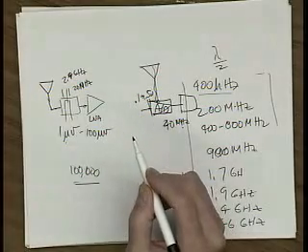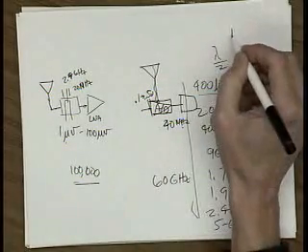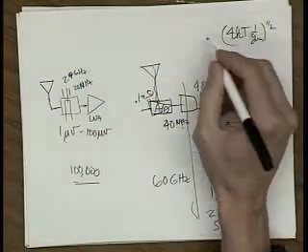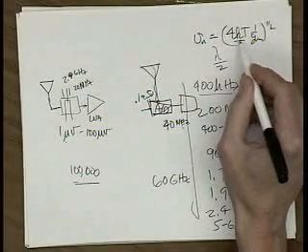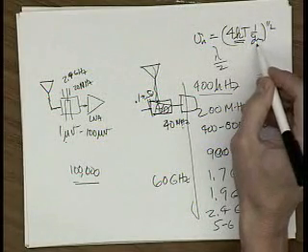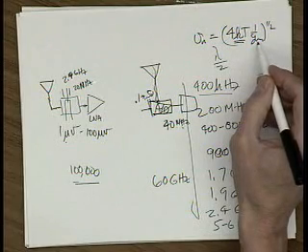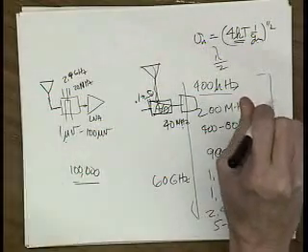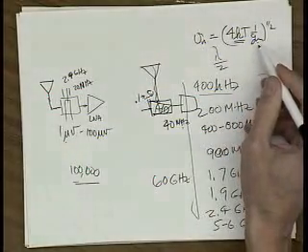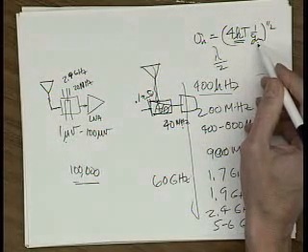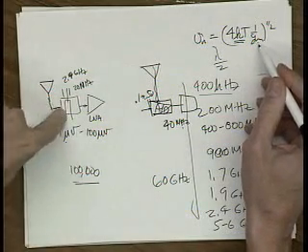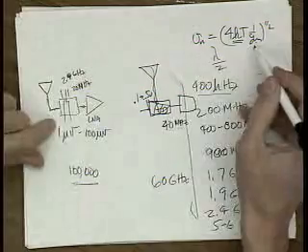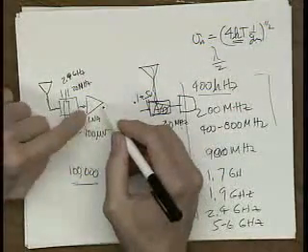So if you think about every transistor, the noise value is roughly the square root of 4kT times 1 over gm. So this is kind of the noise voltage. kT is the thermal voltage, and 1 over gm means as you make gm larger, the noise goes down. So you can see a problem here with power. If you want really low noise, you can do it by making gm really big, but then the power gets higher. Or you make the transistors really big, but then you have a problem with speed, because a really big transistor has a lot of capacitance, so it's hard to drive. So that's all part of the LNA, and I'm going to talk a little bit more about that in a few seconds.